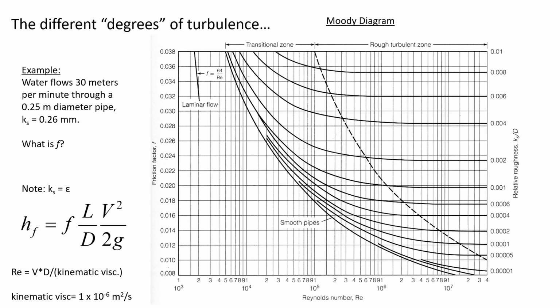So on the Moody diagram, we have to find the curve that is closest to 0.00104. We're going to be maybe a little bit above this curve because this is 0.002. So we follow this curve and look for the point of intersection with 1.2 times 10 to the fifth. Following this curve, looking for the point of intersection, it's right there.